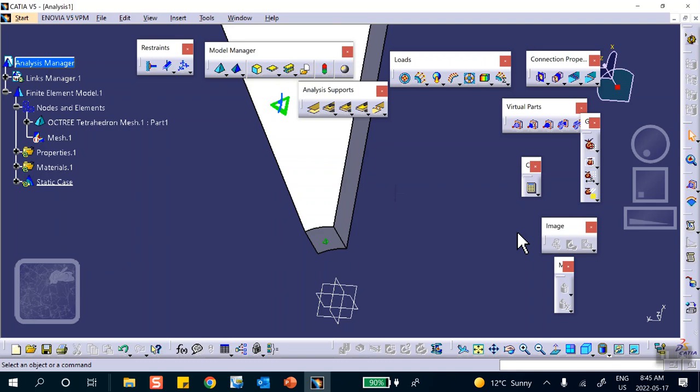There's nothing magic about a plane of symmetry. All that means is that things on that plane do not move perpendicular to it. That's all. So instead of using surface slider, if I took one of these surfaces and said nothing moves perpendicular to it, that'll do the job. I don't need a surface slider. It's the same thing. And that's very easy to do on this one. Of course, you can go ahead and put a surface slider there, no problem. But in the book, on the other one, I didn't put a surface slider. I could have, and I will now.